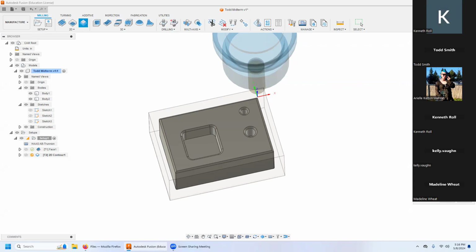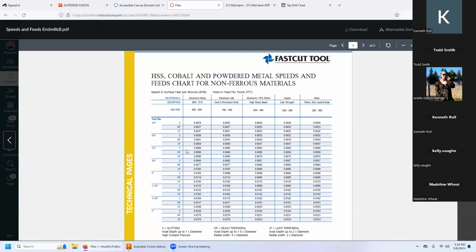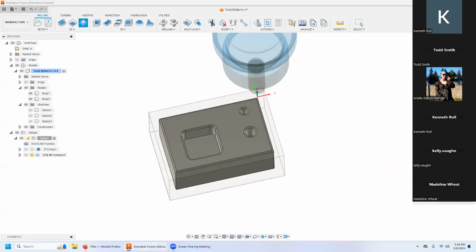And our feed per tooth for a 1/2 inch end mill is 6 thou for good solid rough. And feed per tooth is okay. They were pretty close to what I had going on. Okay. Feeling better. I like that. We're gonna change that plunge to a 20. The ramp should have updated as well. Make sure that's correct. All right, feeling good.